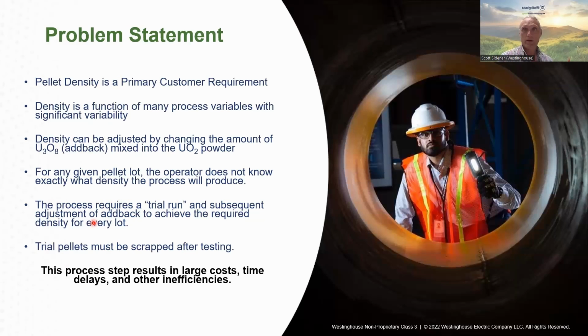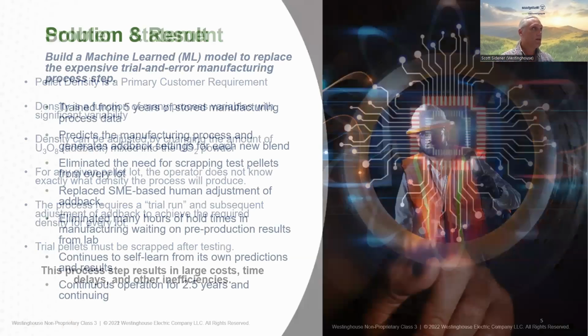The bad part of that is not only did it take time to do that test run, but all of the pellets created in that test run had to be scrapped after they tested them. So it was a destructive test. Every single lot of pellets was causing scrap and cost of poor quality, as well as delays in time.